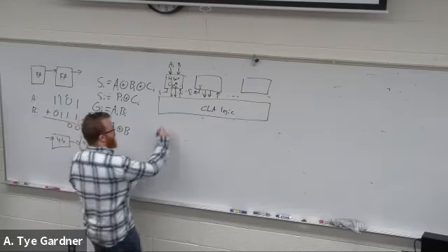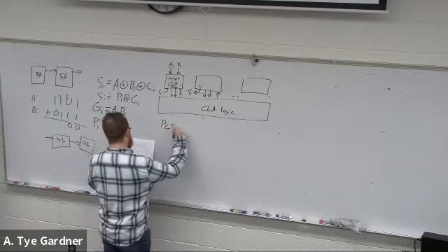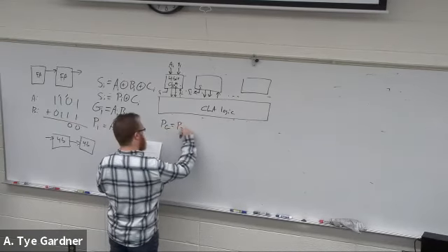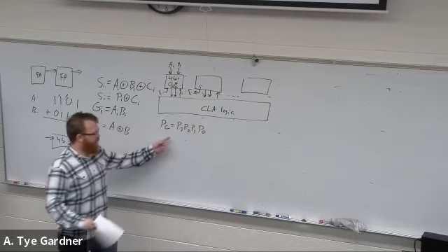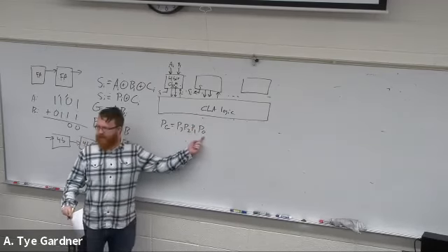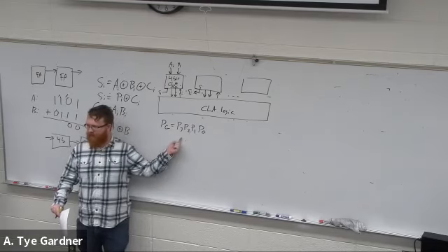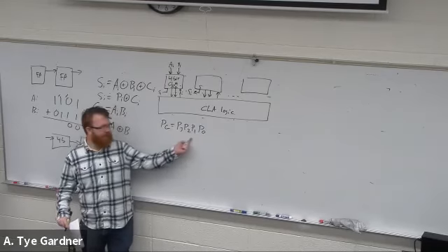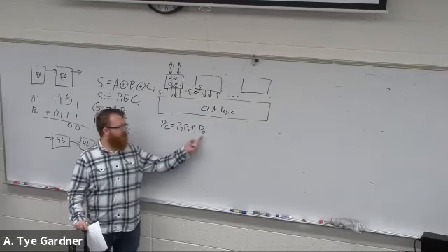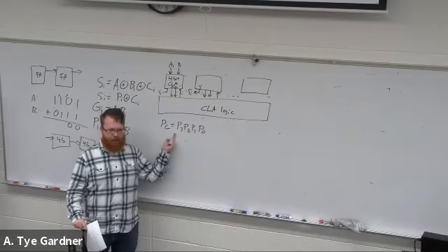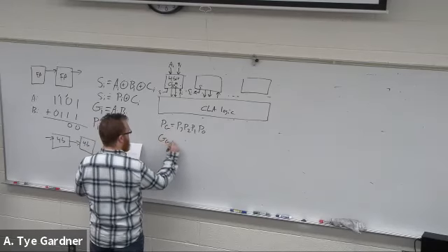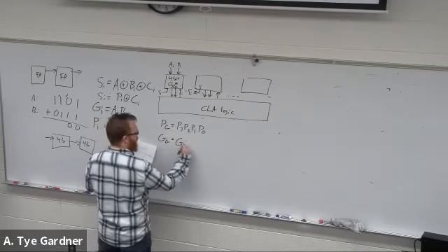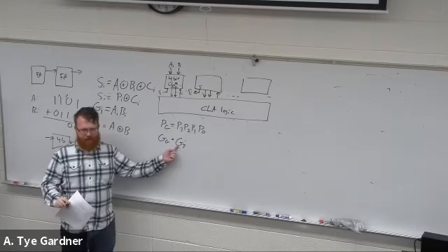And all you have to do for that is my propagate function is, internally, let's look at P3, P2, P1, and P0. Does it pass all the way through? That's the same as those previous equations, but we've rewritten the propagate function into one big one. Then I can write my generate as, did my last one make one?